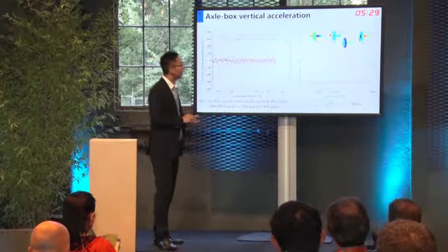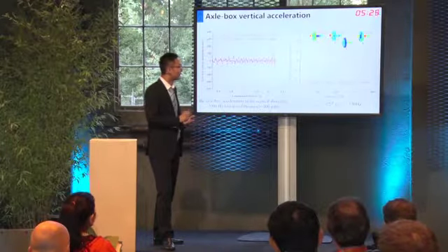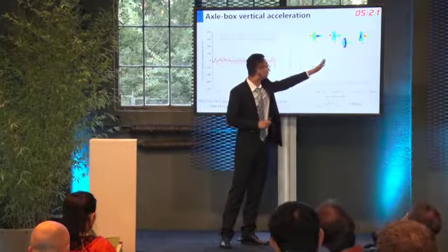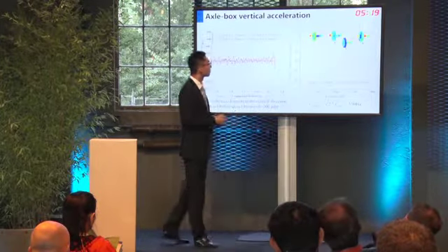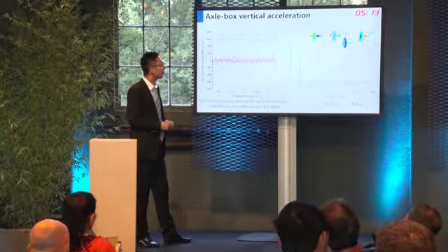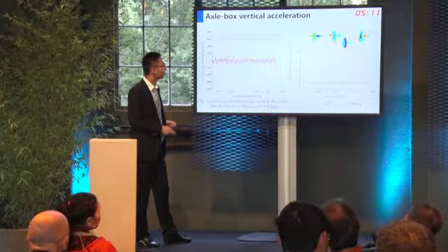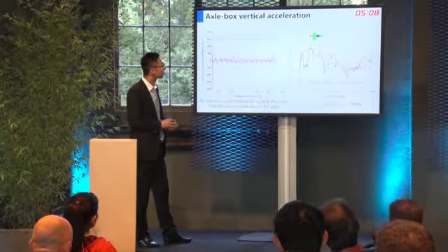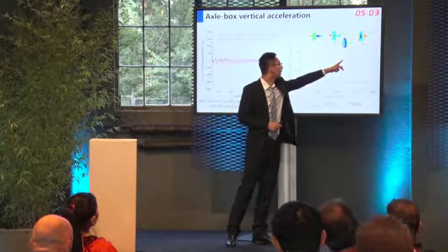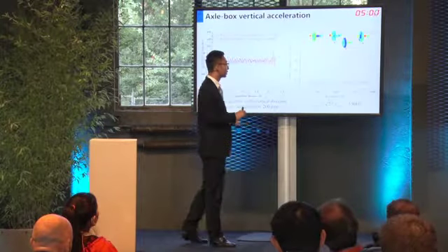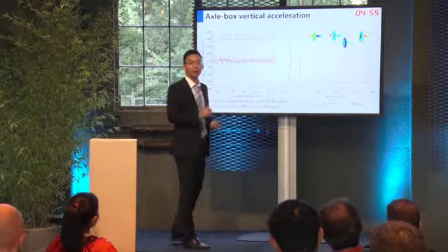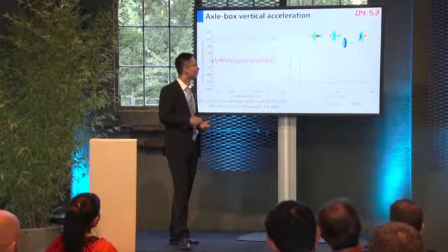So above 550 Hertz, the resilient wheel can effectively reduce the acceleration of the axle box. At some other frequencies, the acceleration of the resilient wheel is a little larger than the rigid wheel. This is due to the influence of the resonance of the axle box.